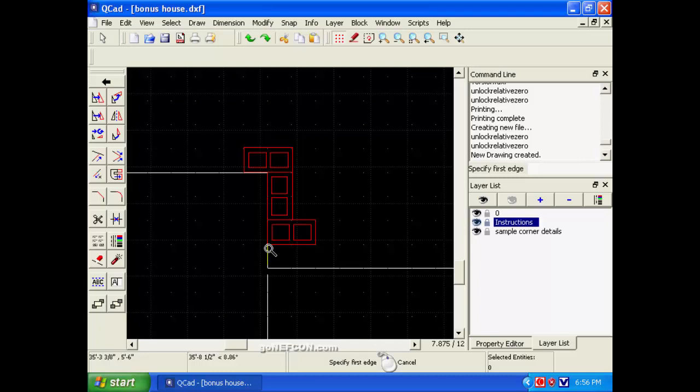But it's even worse than that. It's a block and a half plus this 1/4 of an inch difference between a corner block and a normal 8-inch wide block. So we have to use a number we calculated up there, 1 foot 11 7/8 inches. So the next thing we're going to do, we're going to move this wall and get this wall back where it belongs.